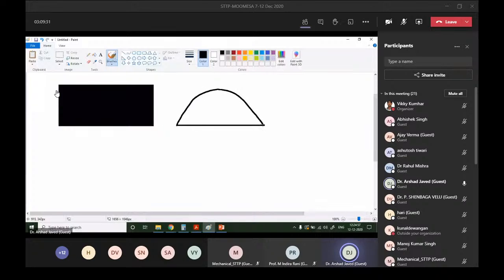These are all published results. So this is a new kind of topology which may generate, just for example. So here you apply a load P here, and these are the two supports. So now here the question arises, what is the difference? This is the example of continuum topology optimization, where we don't make a ground structure. There is no ground structure.